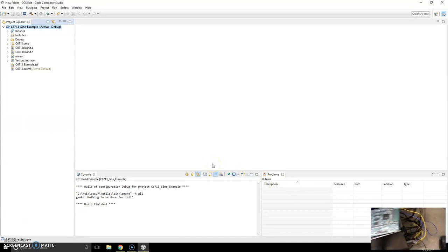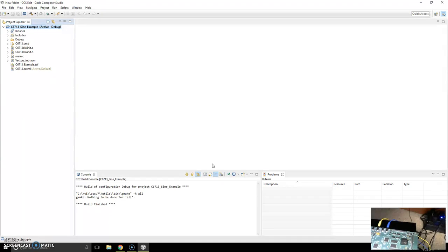The reason why we're doing that is we're going to send a sound out of the headphone jack to the board, and that's going to go to line in. Then that's going to be processed by the DSP and sent out through the headphone jack into the mic jack on the computer, so the computer can receive the processed signal. Okay, so it's important. For this particular example, though, we're really only using the headphone jack, but in some of them we're going to be taking signals in from the computer. So you might as well always just set it up this way.